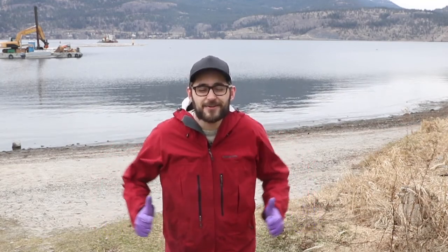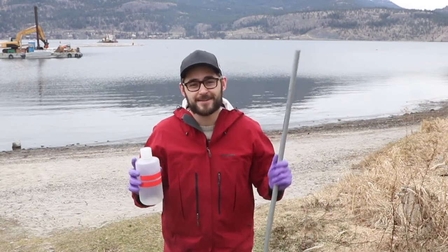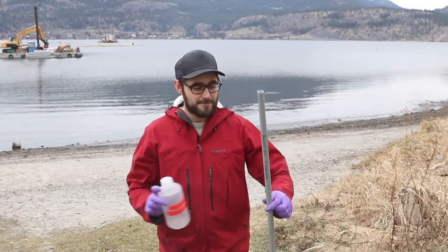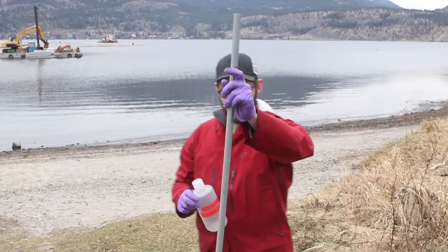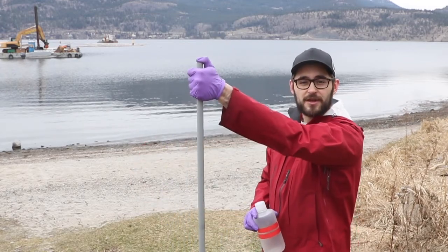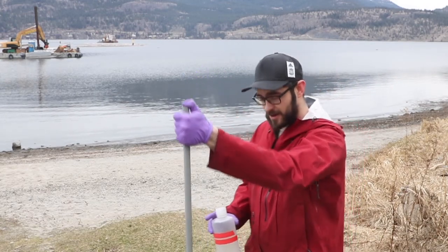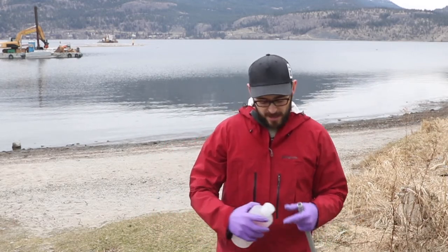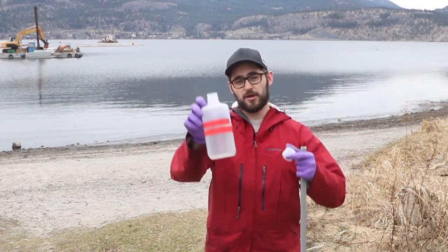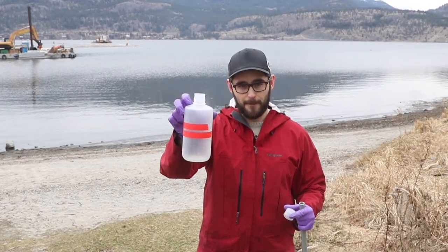Oh hey there, I'm Nick from the Ogopogo Sampling Company, here to explain surface water sampling for you. So we got two methods of collecting the surface water sample. Method one is using this stick, plunging it into the water, and capping the top with your thumb. This will give you a surface water sample down to a meter of surface water. The second way of doing it is just by removing the sampling bottle and moving it in the water towards the current, filling it up.